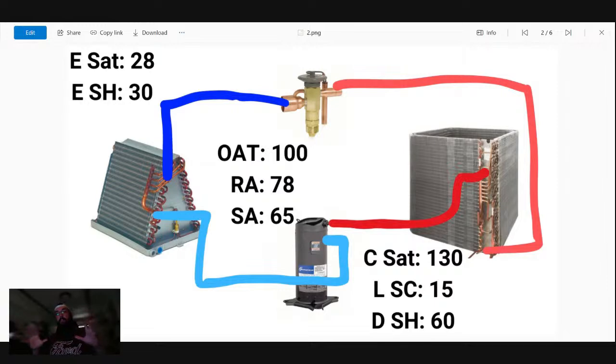Okay. So at this point, we've ruled out a lot of options. I don't think we need to spend more time on it. Let's dive into the valve. There are some other things we need to check. Like I said, over or undercharge, the actual physical components of the valve, the physical components of the system, the dryer, the non-condensables, refrigerant. We've gone through a whole checklist of items, and really we're down to what else could it be other than something with a TXV.